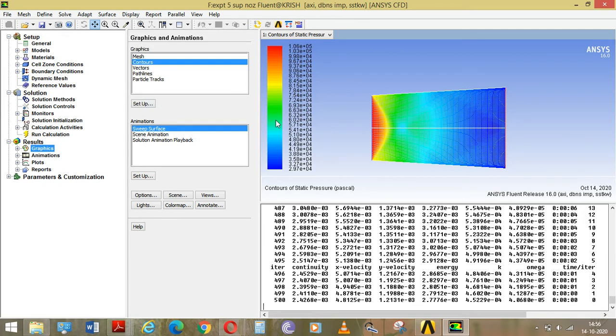That's the difference between a nozzle and a diffuser in supersonic flow. In a nozzle, you'll find expansion waves. In a diffuser, you'll see shock waves. Again, having shock waves in a diffuser is a plus point. The shock waves increase the pressure behind them. That's what we want. I hope you have studied types of diffusers.